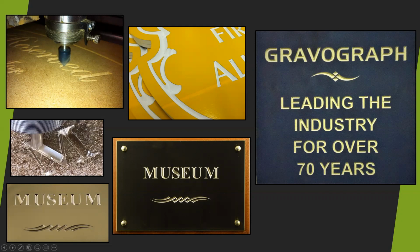So in this case, we say that this is a 2.5D toolpath because not only is the cutter plunging on the Z-axis to control the depth into the material, it's also traveling on the XY axis to carve the contour. And as it reaches a narrowing area, the tool indexes up at an incline to give the final profile. So a standard 2D toolpath would be able to fill at a consistent depth, but not raise the cutter to allow for very thin strokes utilizing the same cutter just by varying the depth. And that's where the phrase 2.5D comes from in this.